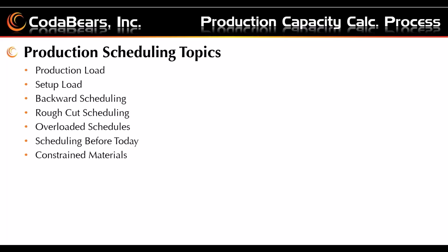Now, by default, most of them go in as normal, but if I have a job that I know is urgent or has to be run, it's an important customer, I may move the scheduling priority up higher. Or I know I have to have these sub-assemblies before another job can run, so I may want to move it higher in the priority. Epicor is going to look at that priority code and the due date for the job to figure out which ones need to go onto the resources and in what order.